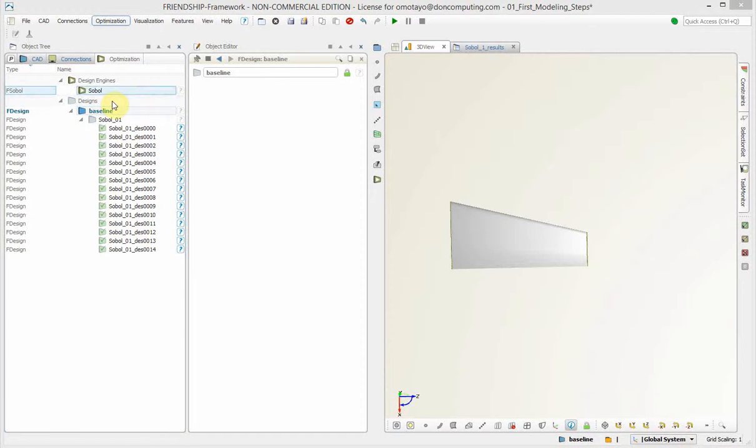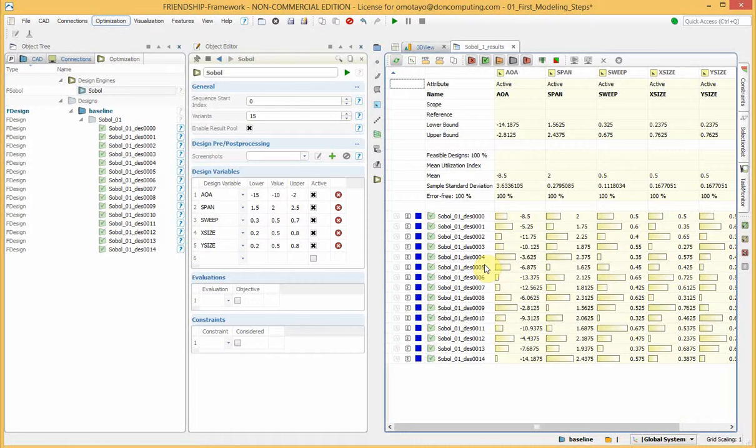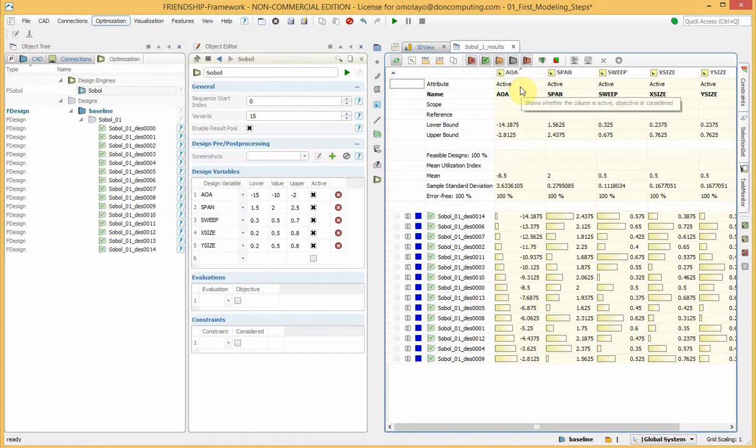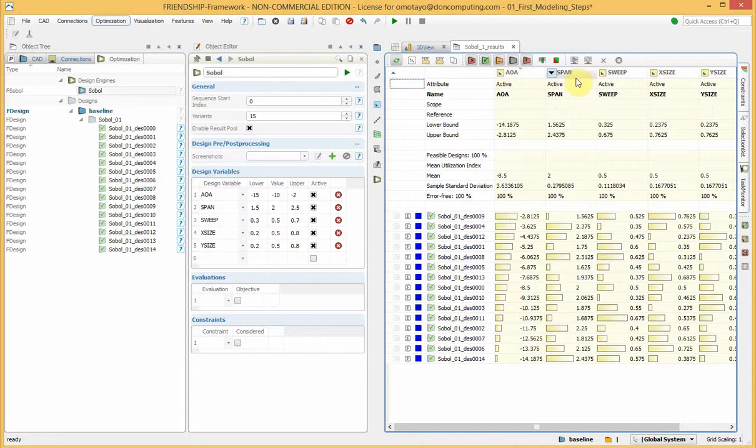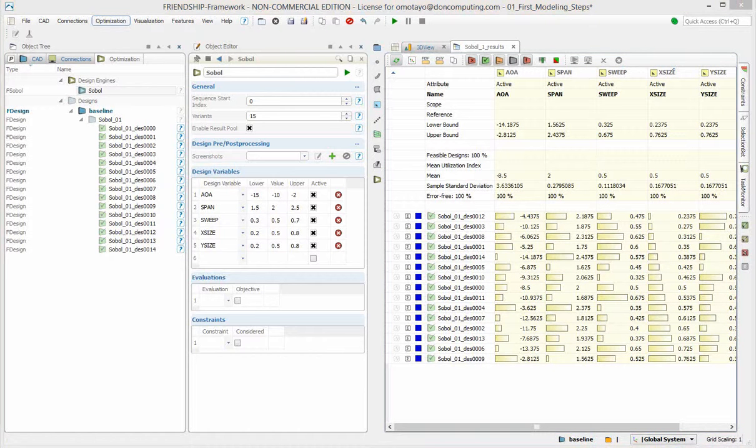The result table provides sorting mechanisms with regard to its entries as well as creation of PDF reports and plotting of 2D and 3D diagrams. These functionalities are available via the drop buttons of the table toolbar. For sorting with regard to a certain design variable, just click on the header of the design variable once or twice for increasing or decreasing order, respectively.